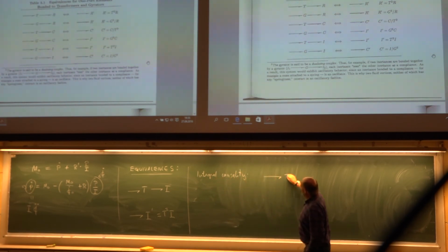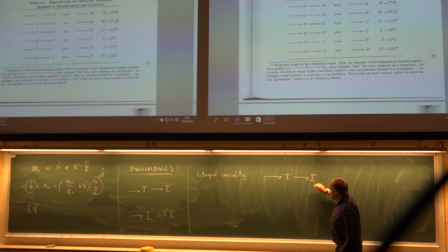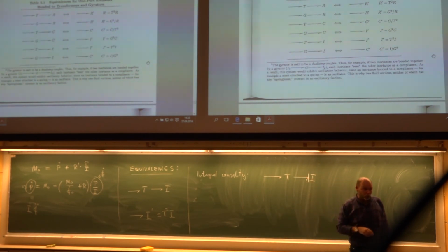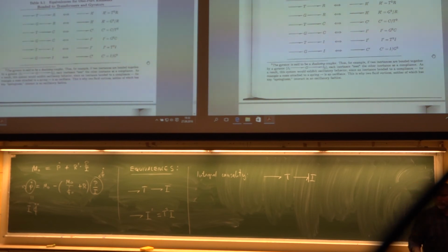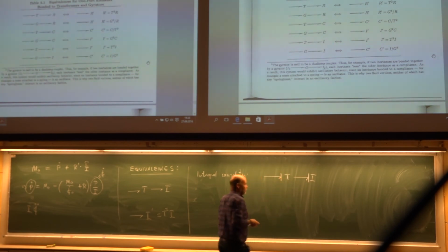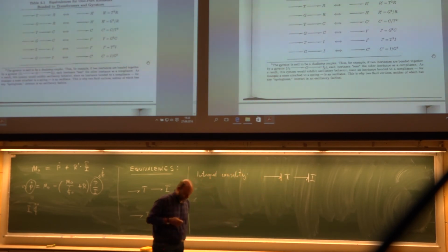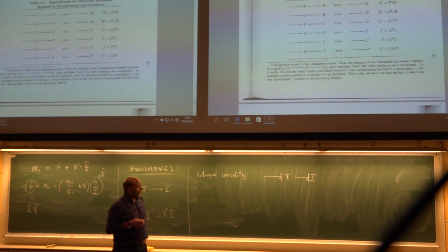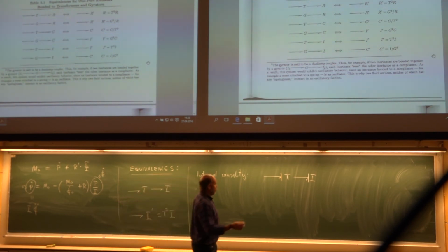How was it then? Well, for the inertance, I want the causal stroke to be towards the inertance, like that. A transformer doesn't change the order of the causal strokes, hence it has to be like this. Now say you know the flow.